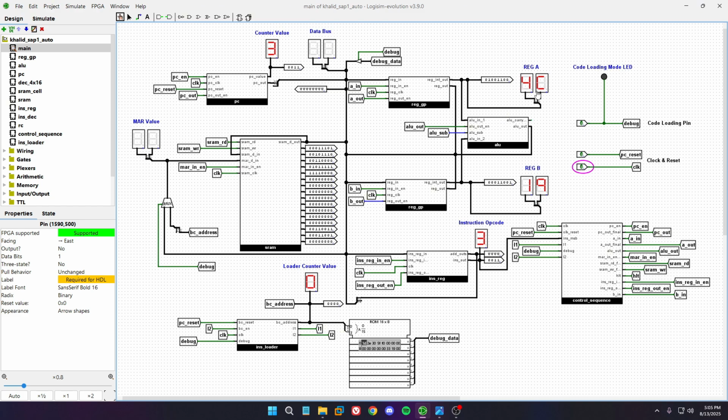So now we have the addition stored in register A. Now another 5 clock pulses and we can store this value into our memory address 15. You can see our register A value has been stored into memory address 15.